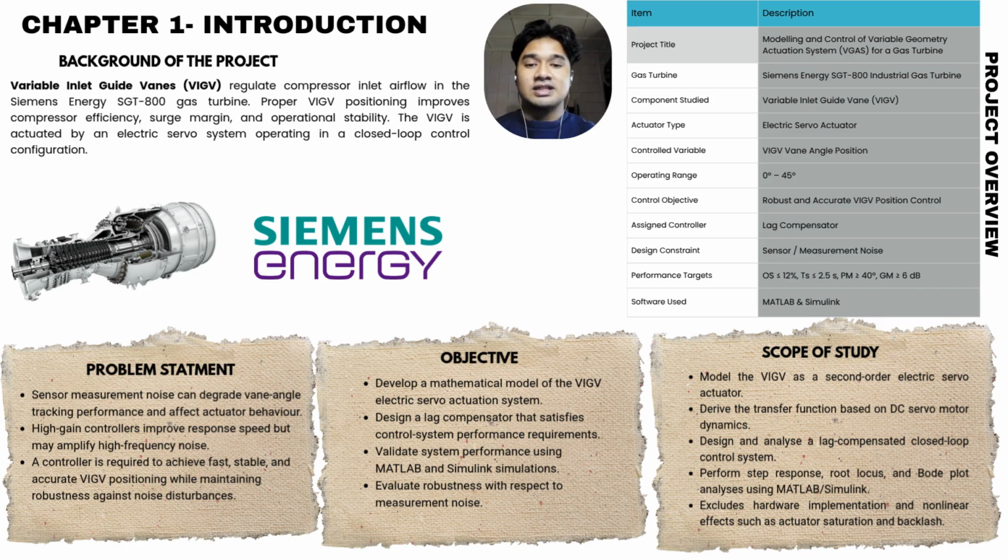The lag compensator is selected because it improves low frequency tracking performance while limiting excessive amplification of high frequency sensor noise. This study focuses on modeling the VIGV as a second-order electric servo actuator and evaluating the compensated system through the step response, root locus, and frequency domain analysis.